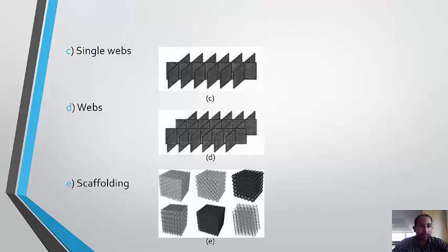Then comes columns. For isolated small islands, column type support structures can be used. Zigzag and perimeter support. The zigzag and perimeter support structure is most suited for FDM prototyping with a continuous path for each layer.